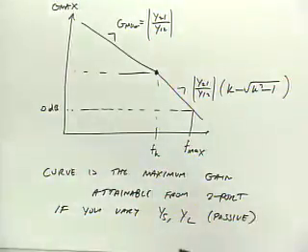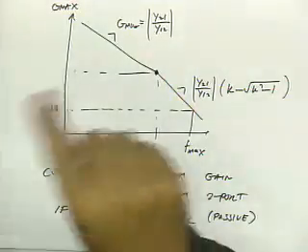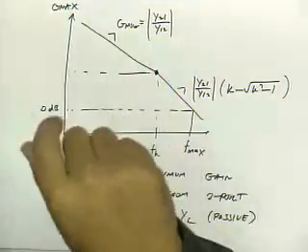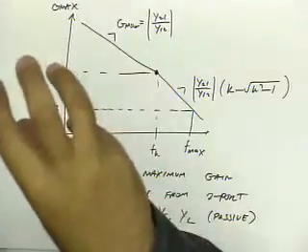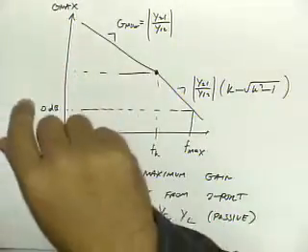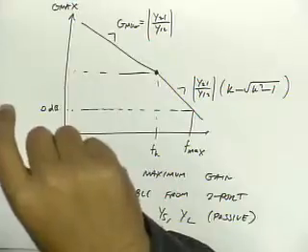At low frequency, the C mu should be an open circuit, right? Why is there a feedback? Good question. It's because there is a feedback path present, and there's lots of gain in the device. So I can pick a termination so that the loop gain of the device becomes bigger than 1, right?